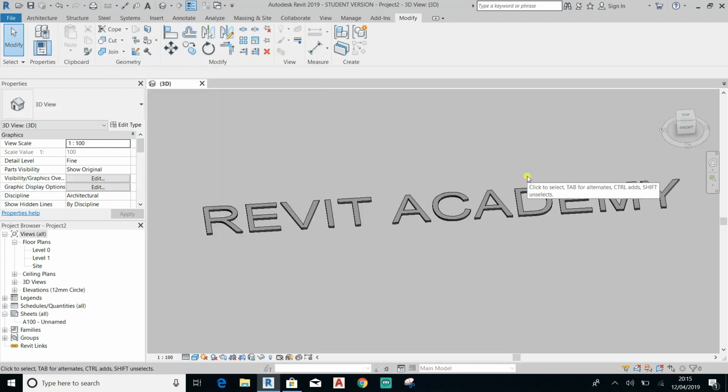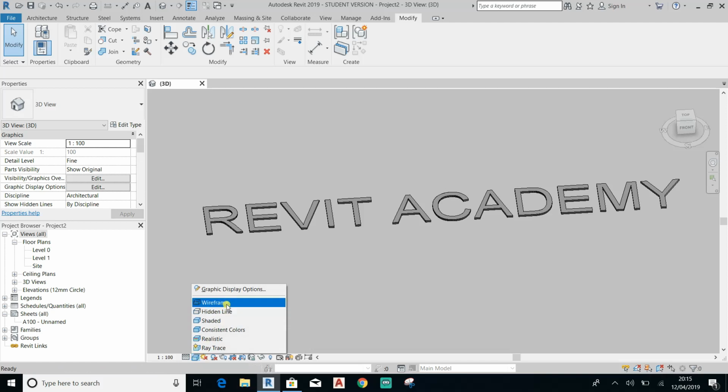So moving on to the status bar at the bottom here. If you can see here, the status bar. This is where you can make adjustments to your view. Select the level of detail. So you've got options here. You've got a wireframe option. You've got hidden. You've got shaded. You've got a constant color. You've got realistic and ray trace.